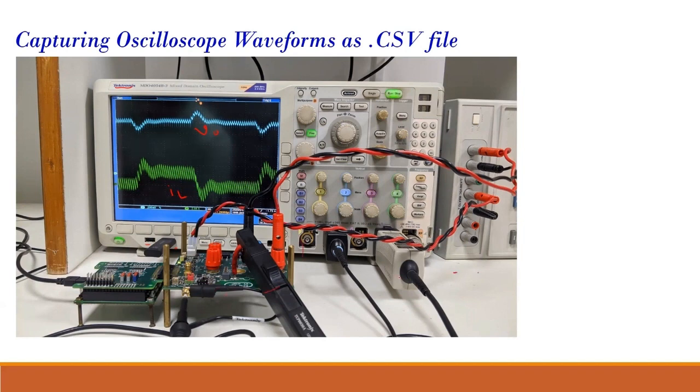This is your power supply. This is your current probe. And this is your voltage probe. Okay, so your current probe is like a clamp around this sort of wire, so that it can show your inductor current. This is not your sensed inductor current. This is your displayed inductor current. It is displayed via this current probe. And this is your output voltage, which is displayed by this voltage probe.